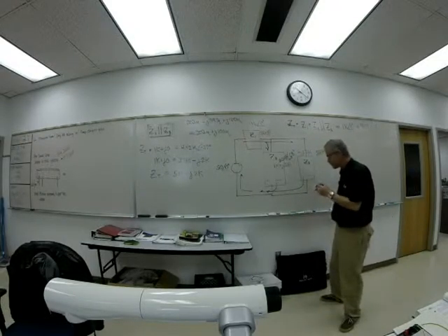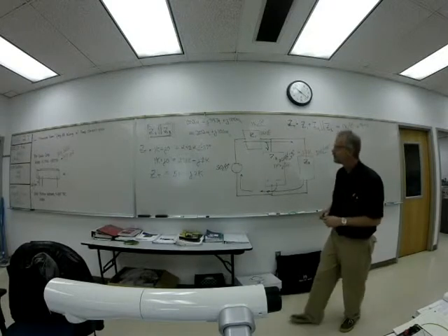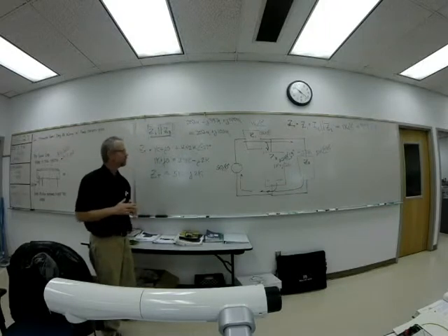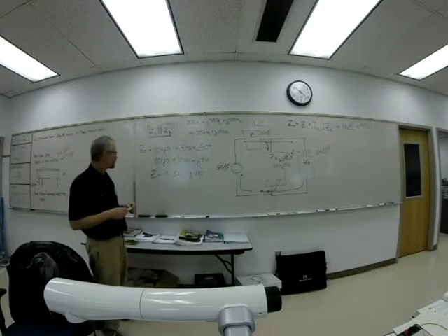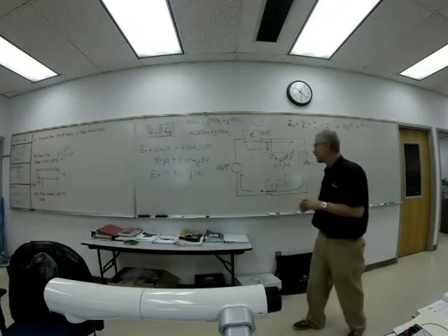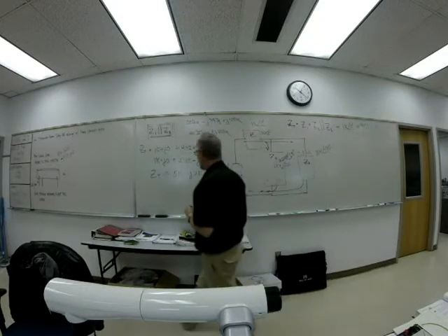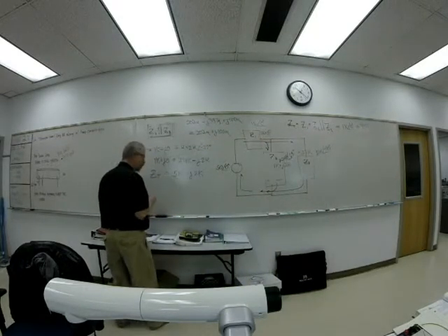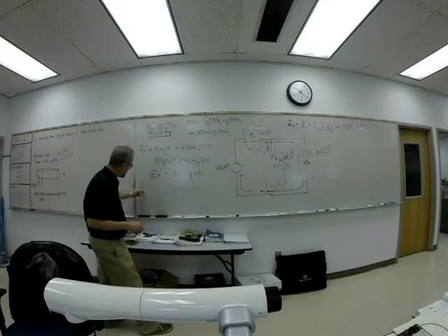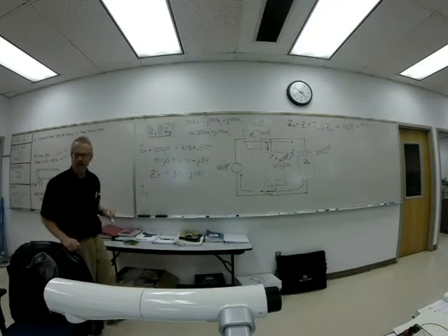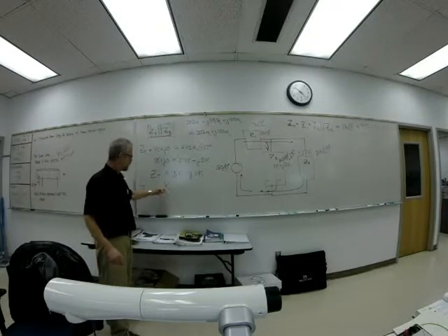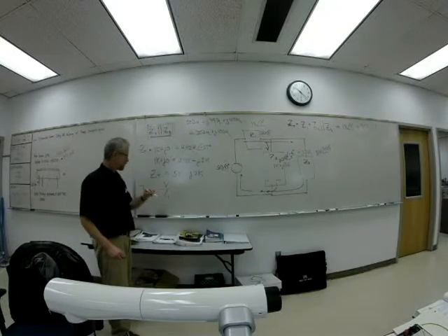And convert that back to polar. Why would we want to do that? I don't know, that's what we've been doing. We might end up having to, who knows? Probably not though, since we don't have to add or subtract that to anything. But we will have to go back to polar because what we're going to have to calculate is the total current. What's the total current equal to? IT is equal to what? Ohm's law says it's equal to V over R, but in our little microcosm here, V over Z. V over ZT.